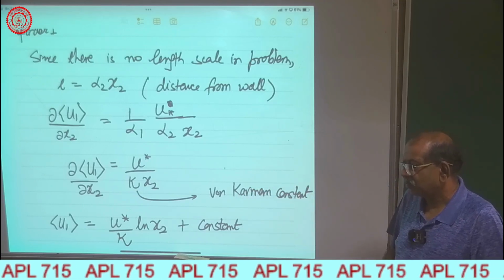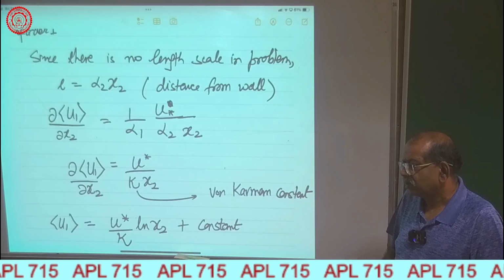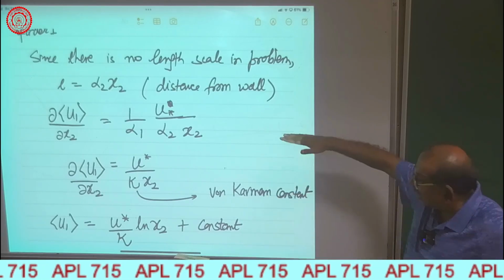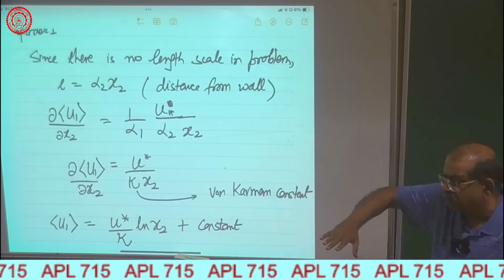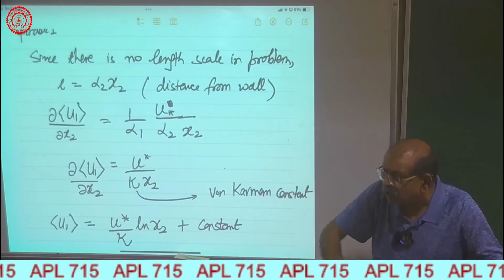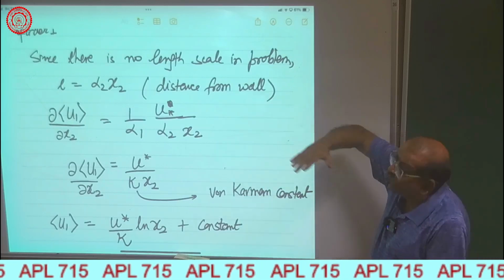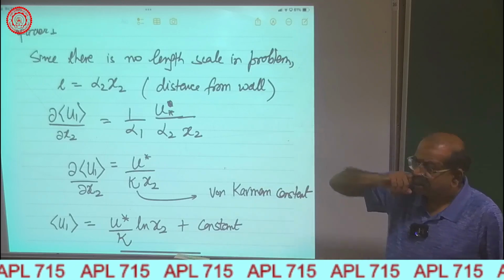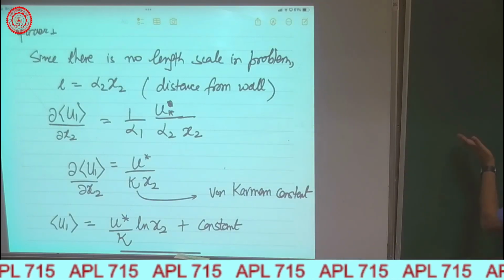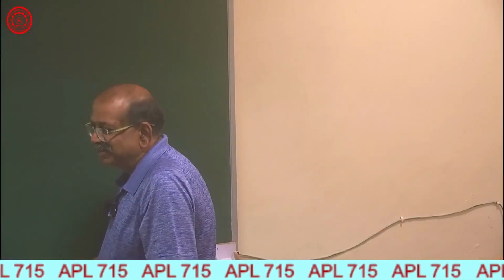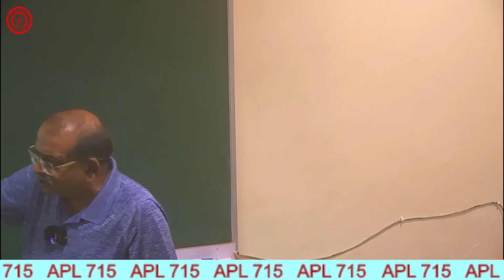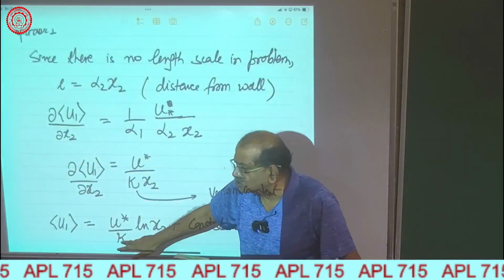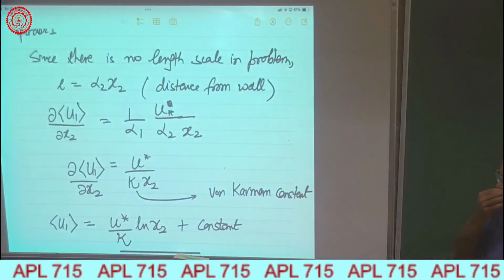More or less in all the flows we get this. No, yeah, but we will show that. What I meant was without suction. That is, flow in a pipe, flow in a channel. This was flow next to a wall. You always get this log layer. And there's a form of log layer which even comes in flows with suction. But in flows without suction, you always find a log layer. And more or less this constant is also almost universal.